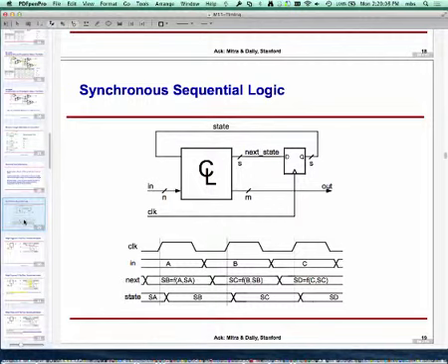What you care about is contamination delay and propagation delay. If you hear the term minimum delay, from me or anyone else, ignore it. It's a useless quantity. You will see why contamination delay and propagation delay matter. The only reason I brought it up is because people loosely refer to that, but it has no relevance as far as the rest of digital design is concerned.